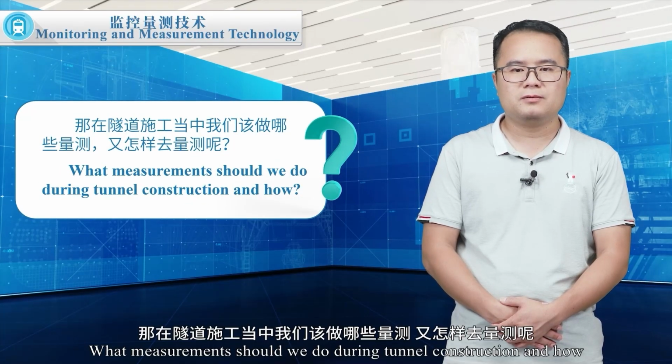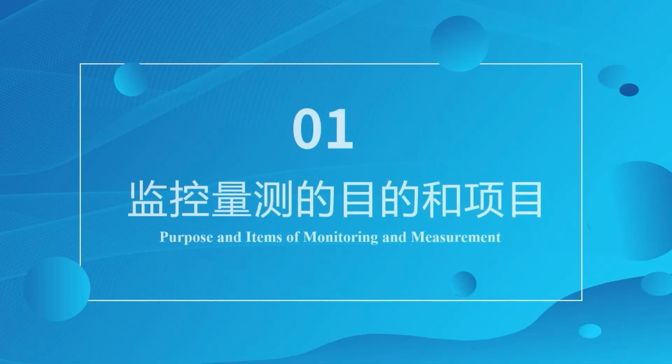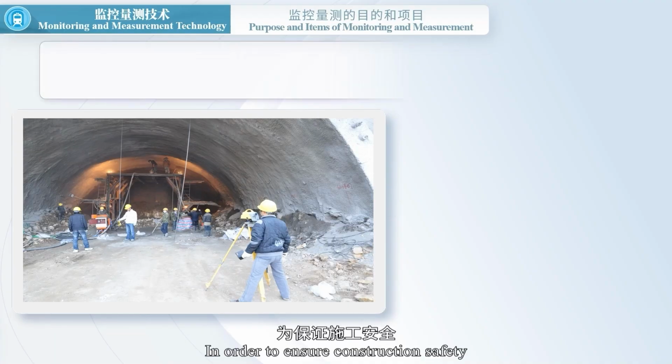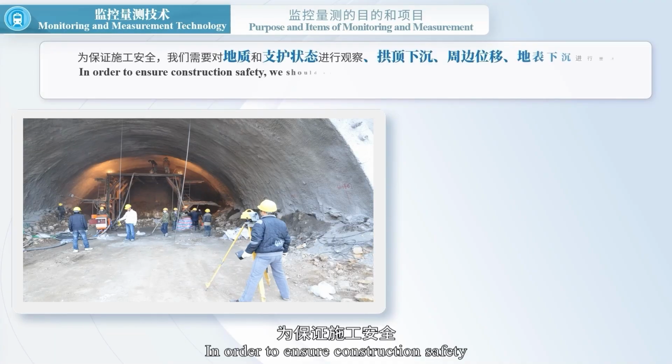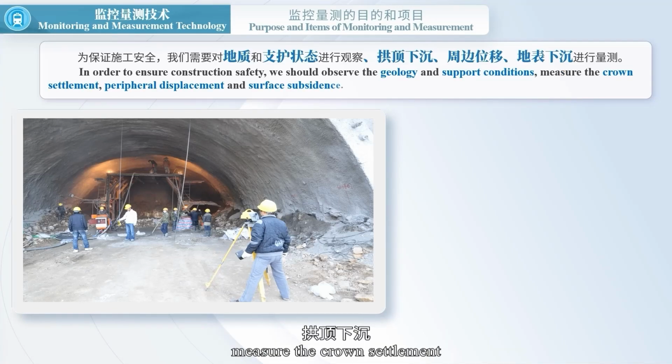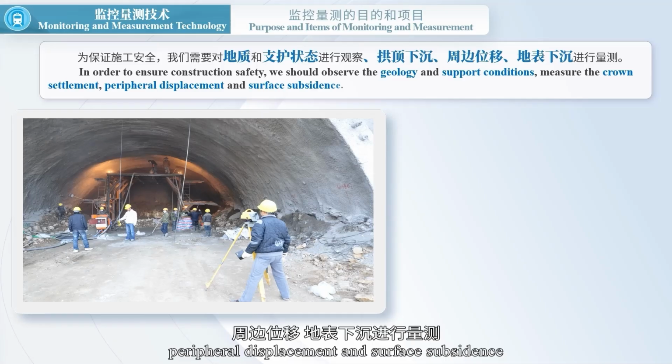What measurements should we do during tunnel construction and how? In order to ensure construction safety, we should observe the geology and support conditions, measure the crown settlement, peripheral displacement and surface subsidence.